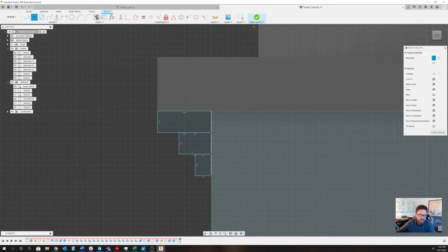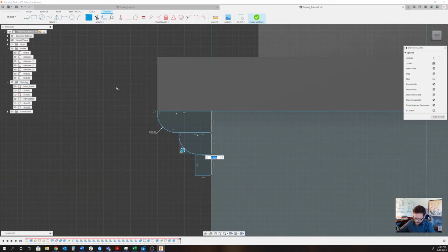Okay. The tool that I want you all to use to round things off is the fillet tool. So I'm going to grab that, pull this in until I've eyeballed it, maybe 0.35. And that way I can do it to all three of these. Well, at least those two. Go back to 0.5 maybe, and do it to all three. Sketch.